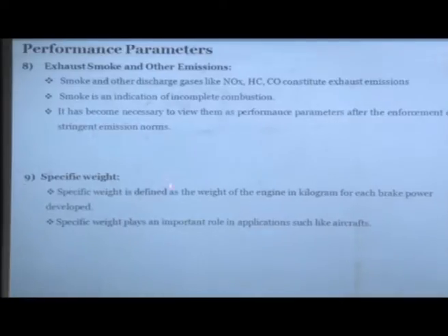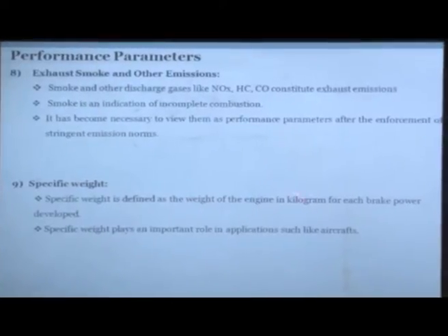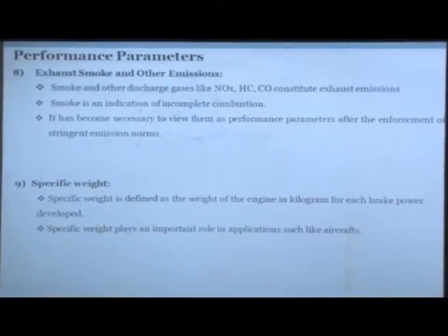Specific weight, a very important parameter. It is defined as the weight of the engine in kilograms for each brake power produced. That means how many kilograms of engine weight will produce 1 bhp or 1 kilowatt of power. So that's the specific weight.